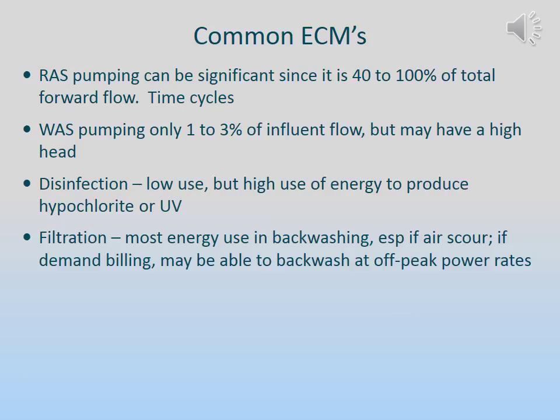Common ECMs. Another process-related energy conservation measure includes the return activated sludge pumping. This process involves being able to pump a volume equal to 40 to 100% of total forward flow. We may want to consider time cycles. Most of the time, many systems already have VFD control, so it may be a matter of maintaining a certain blanket depth. Consider time cycles, but cautiously, so we do not impact the process itself.